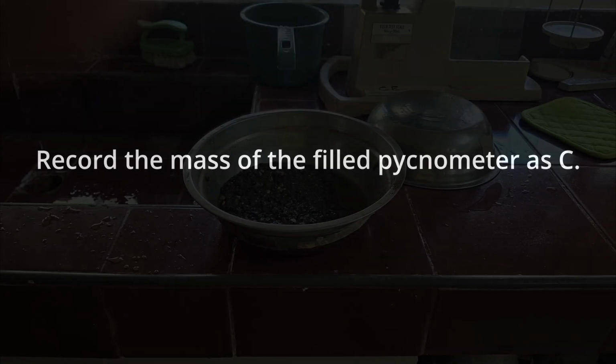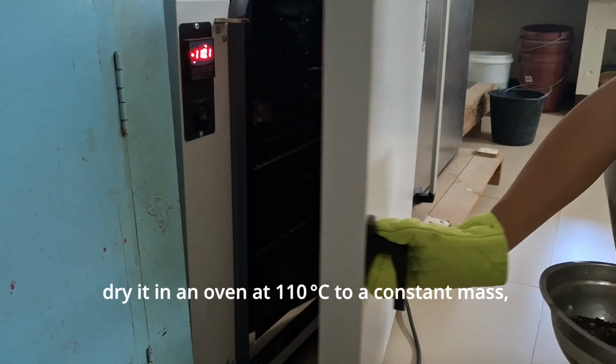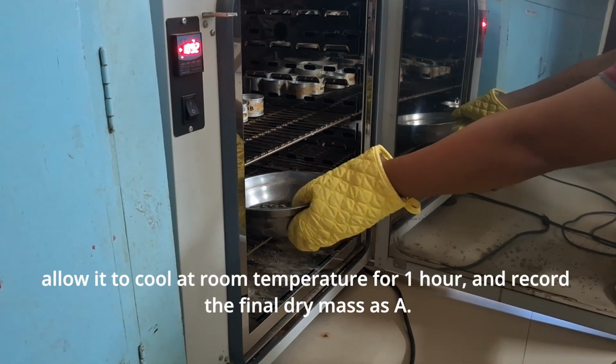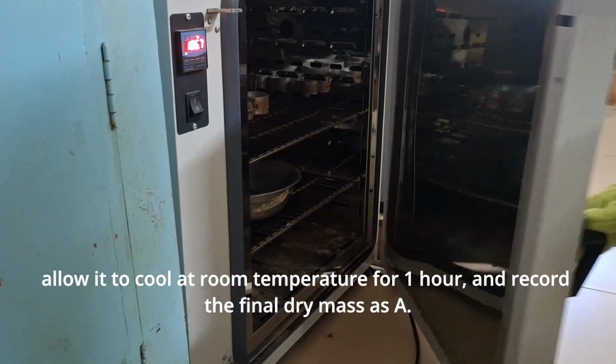Record the mass of the filled pycnometer as C. Lastly, remove the fine aggregate and dry it in an oven at 110 degrees Celsius to a constant mass. Allow it to cool at room temperature for 1 hour and record the final dry mass as A.